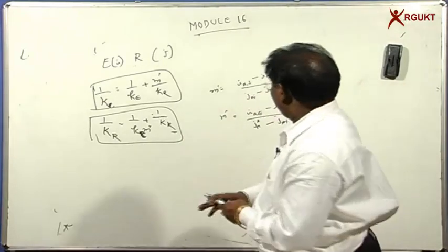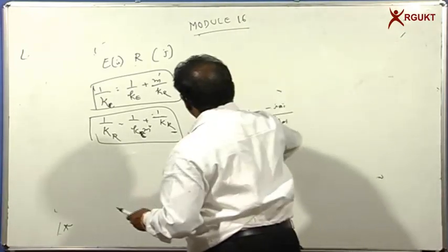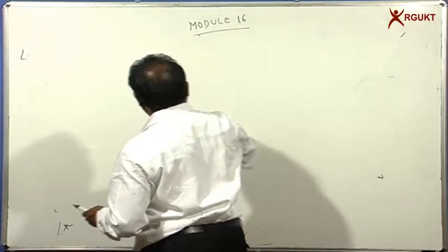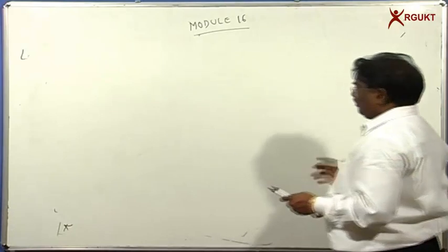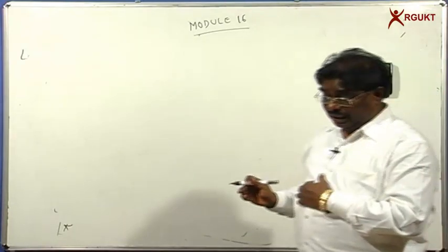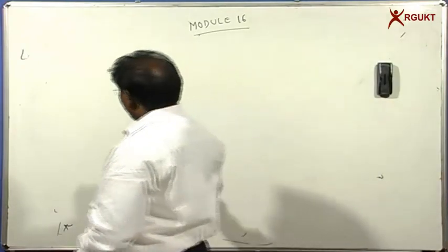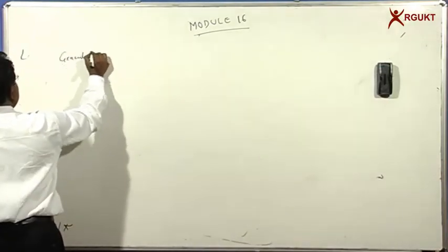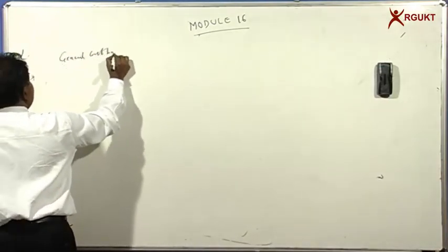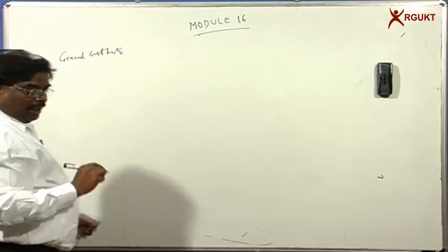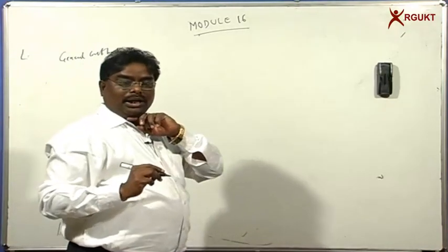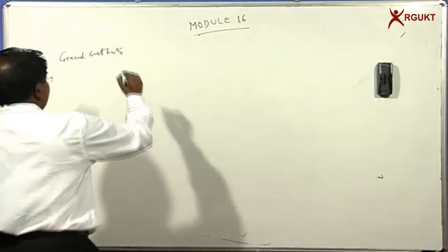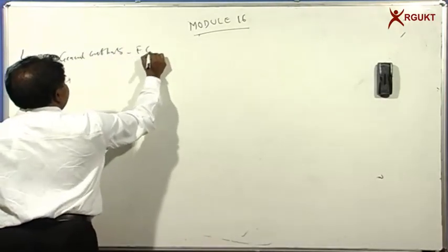Then sometimes these K values are special cases, as you know. Either they may be applicable for equimolar counter diffusion or non-diffusing B. If a system does not come under either equimolar counter diffusion or non-diffusing B, then we have to use the general coefficients. Those general coefficients we call F coefficients.